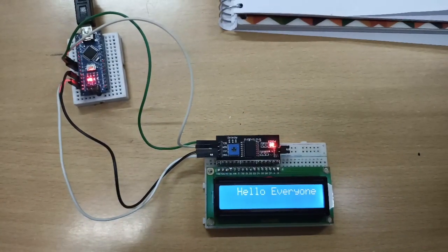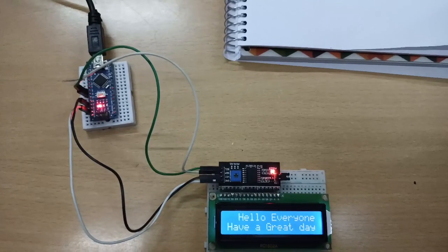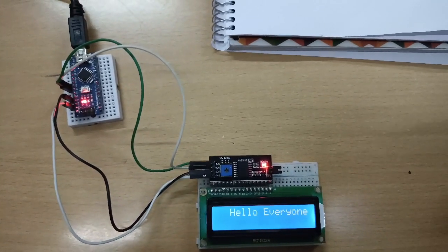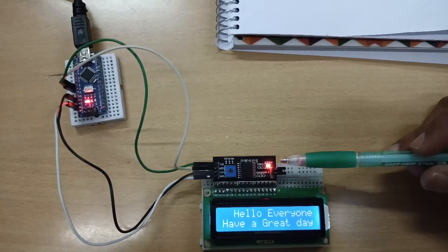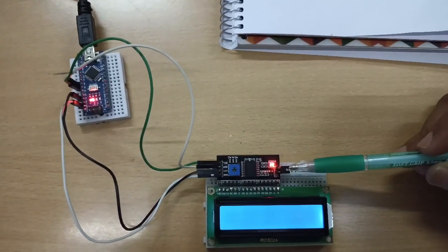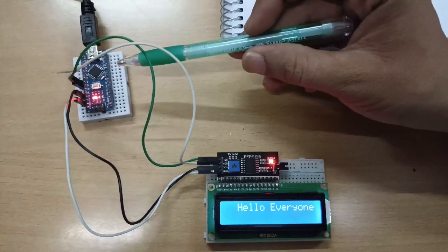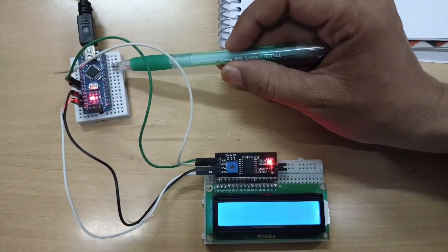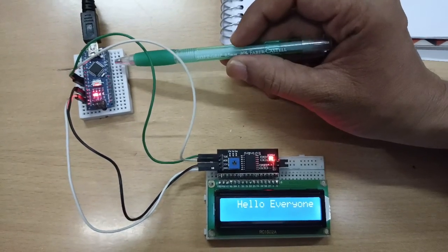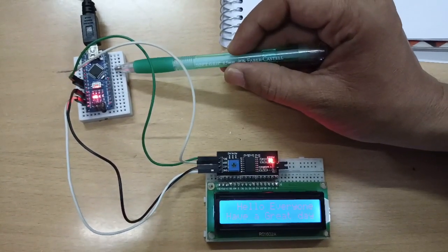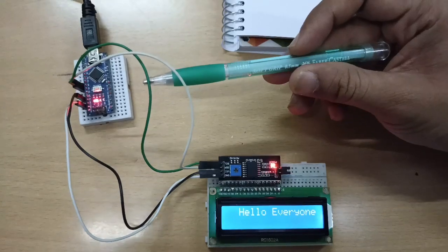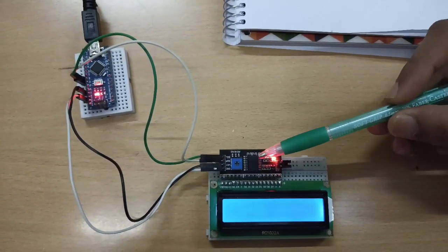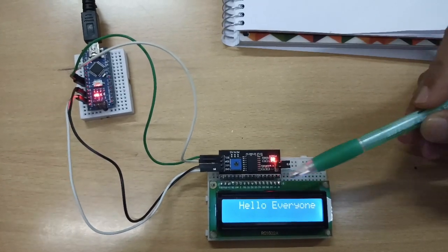Hello everyone. In this presentation, we are going to discuss how to interface an LCD module through a PCF8574 I2C to parallel port data converter along with the Arduino Nano microcontroller. The very interesting thing to understand in this presentation is that from the Arduino Nano board we are getting only two wires which interface with the PCF8574, which is an I2C to parallel port converter,